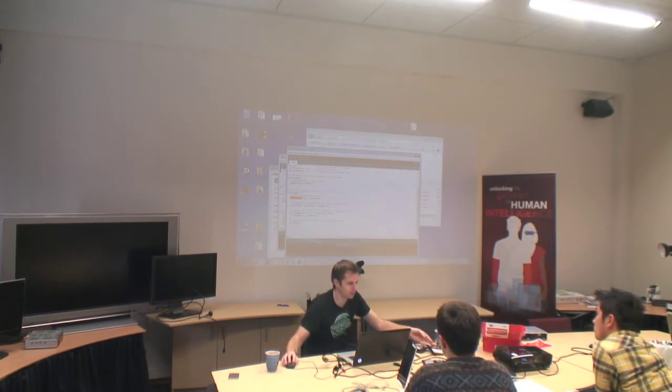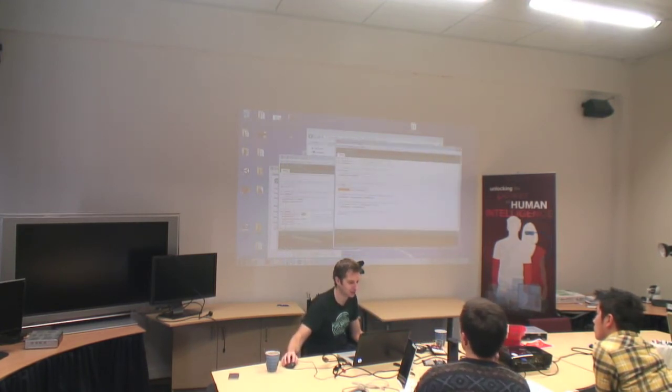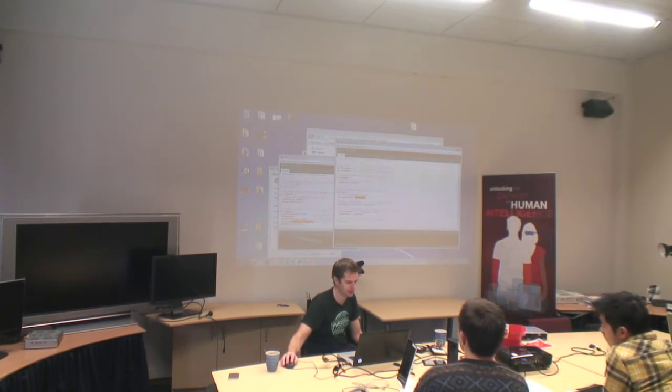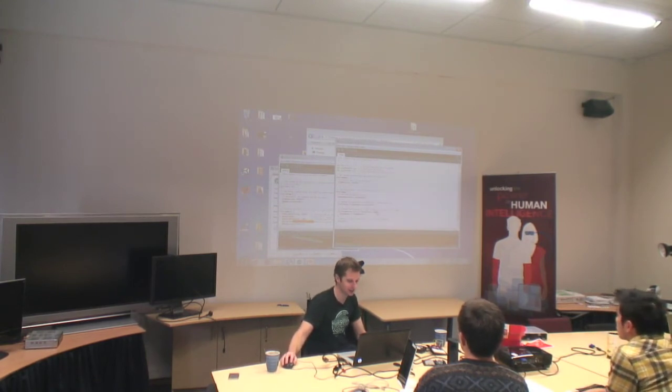And really, it's exactly like the digital write here, so we specify what LED, but instead of saying high or low, we pass in a number from 0 to 255. And in this one, it just basically increases the amount of brightness until it reaches 255. And then it decreases the amount of brightness until it reaches 0, and then it goes back and forth between the two of them. So we can fade our lights in and out by using this analog write value.